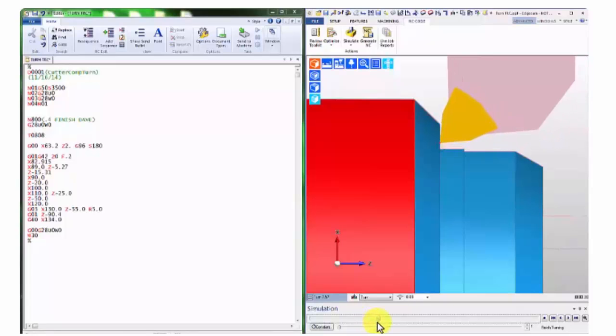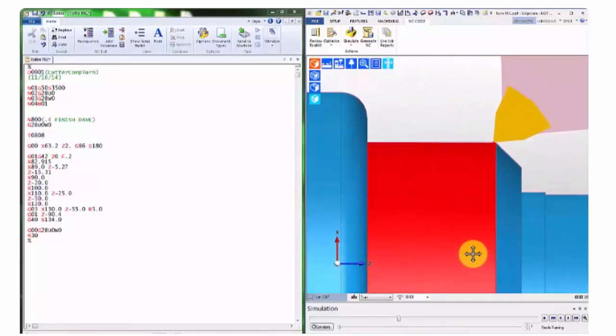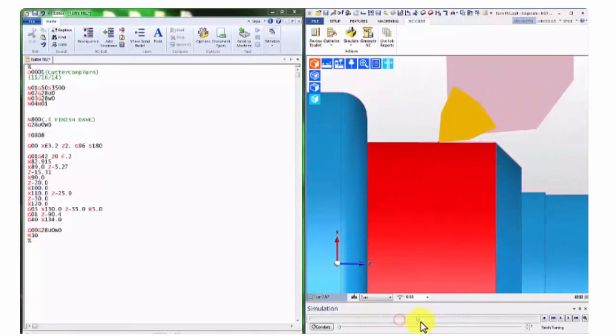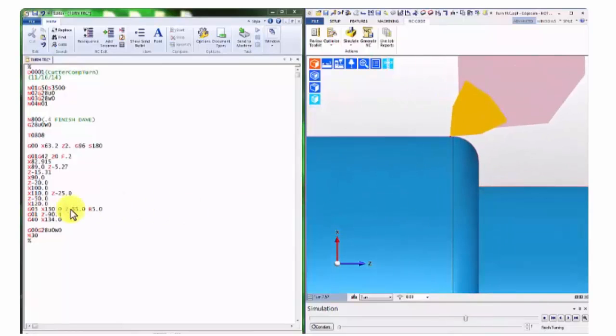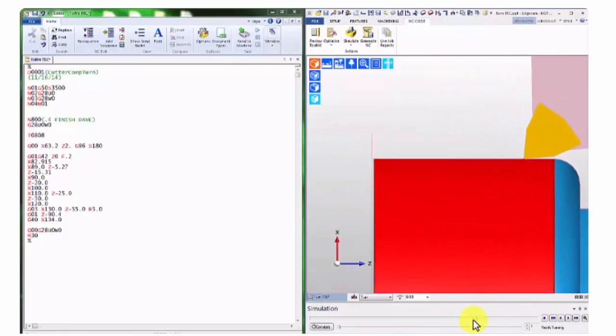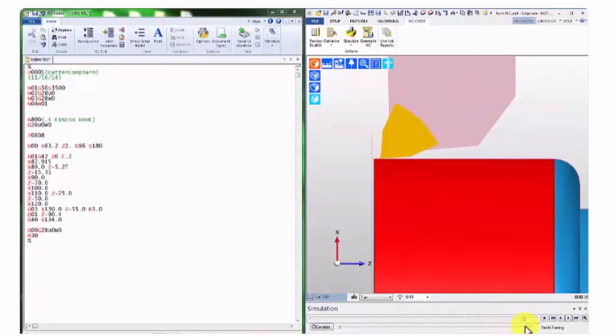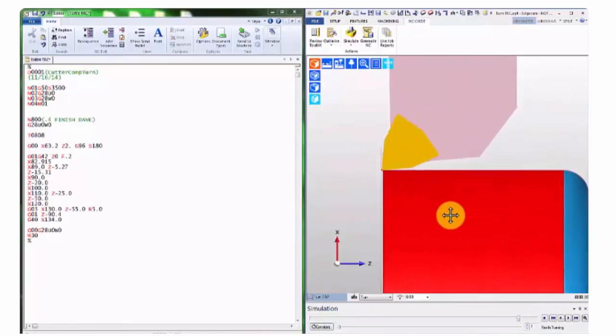And then we're going down in Z, up in X, X and Z. Then we're going down in Z again to there, up in X, and then we've got this G3 command, which is a 5mm rad. It's going to go around that 5mm rad there and end up at that point there. Then it's got a Z move to 90.4, and it will complete this move. If you remember what we said, it actually takes that rad past there.